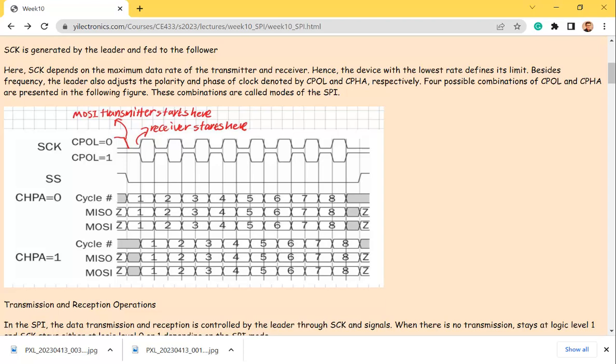And you want to communicate, because this is an SPI module, so it has to be an SPI port. Okay, but SPI is serial parallel port? Serial. No, it's not parallel. Parallel means you have all the 8 bits being sent out at the same time and received by, say, a shift register, like parallel in, parallel out.